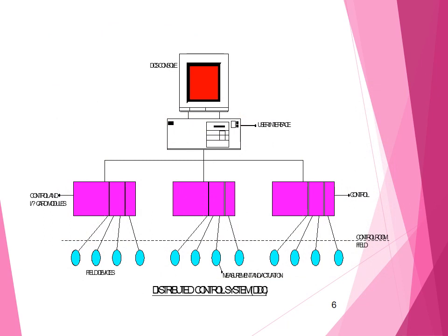This is the modern architecture of instrumentation system in the control panel. Now you see the field sensors are in the field that you can see at the bottom section. Then cables are taken to the data acquisition modules in the panel. So these modules collect the data, process it and send to the central computer. This is the system architecture nowadays followed in most of the power plants.